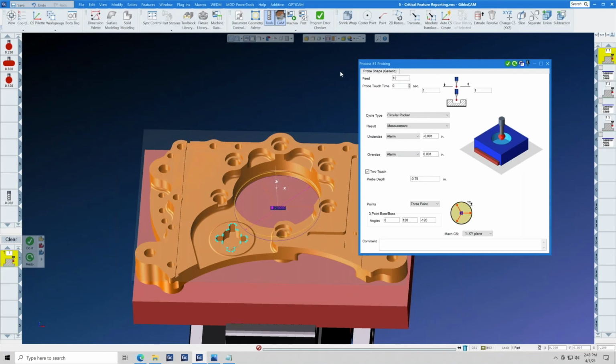The summary of today's webinar is simply this. The profit impacts of in-process probing are: in your part and tool setting, you can reduce your setup times by 90%. Probing is automated and more repeatable than manual methods. A more reliable setting process means less downtime once production starts. When tools are replaced, resetting will also be faster and less error prone. When we use the cut, measure, cut technology, the probe gets it right the first time.